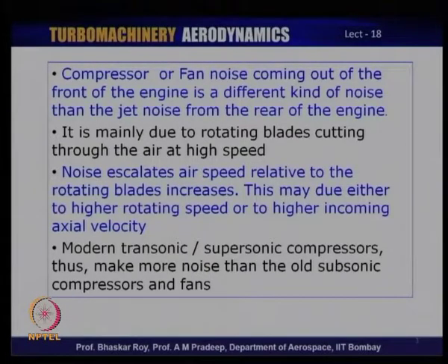Now, as we have seen, this relative speed or relative velocity, or relative Mach number, may increase due to either an increase of the rotating speed or due to higher incoming axial velocity coming through the intake of the engine. Either of them could increase the relative air speed relative to the rotating blades.